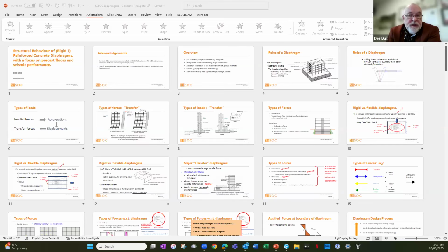Just assume that they're not there for the tension field. But if you've got an in situ floor, the answer is yes. If you've got an in situ floor, which is relying on the top steel to provide moments for gravity support, the presence of axial tensions in the floor will diminish the gravity carrying capacity of a purely in situ floor. Yes. Not for precast, but for total in situ floors, yes.